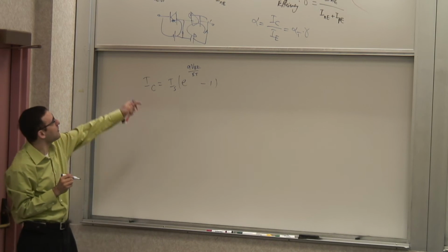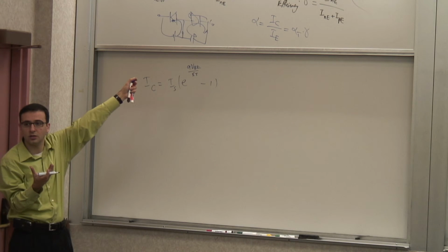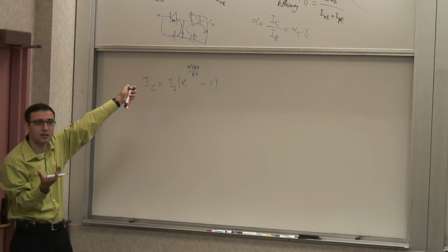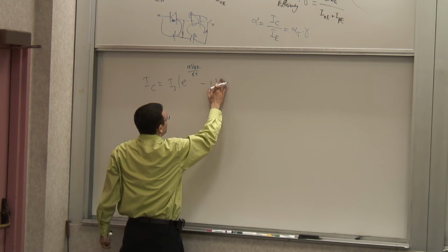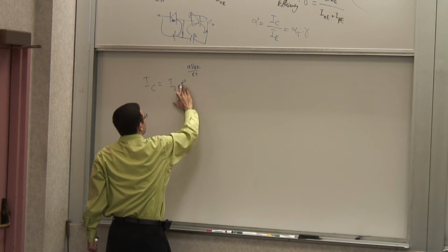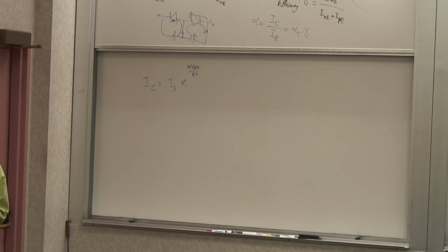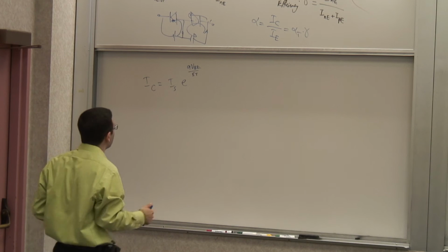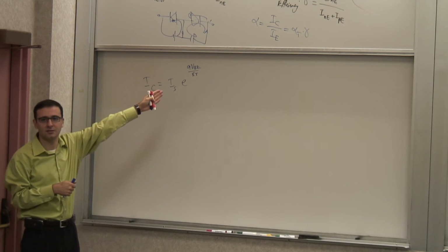And if you operate the transistor in this mode, we know that VBE is relatively large to carry a reasonable current. So this term is substantially greater than that term. So in the forward mode of operation, it's approximately just this, because that term is orders of magnitude greater than minus 1. If you want to keep it in there, you can, but we never do. So this is a very good approximation.